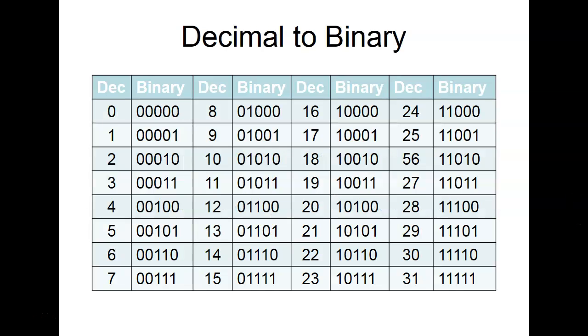So we need to know the difference between this. We don't actually need to know it, but we need to know when they start talking about these encoders whether it's binary or gray code. The problem we have with binary is a term in digital we call propagation delay. This is how long it takes these counts to propagate through a circuit. And the more bits you have, the longer it takes to propagate through the circuit, the more bits that change.